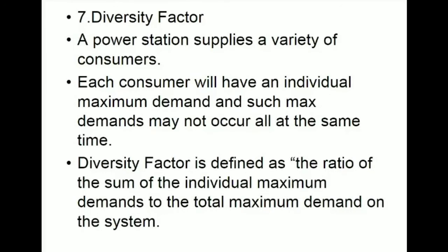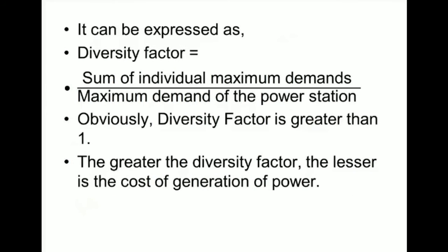Diversity factor is defined as the ratio of the sum of the individual maximum demands to the total maximum demand on the system. So the factor gives the idea of how much the consumers are diversified. It can be expressed as diversity factor is equal to sum of individual maximum demands divided by maximum demand of the power station. Obviously, diversity factor is greater than 1. The greater the diversity factor, the lesser is the cost of generation of power.